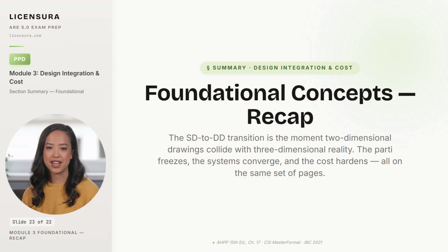If you remember one thing about design development, remember that it is not a polish phase. It is the moment 2-dimensional drawings collide with 3-dimensional reality. The party you sketched in schematic design freezes into a fixed armature. The engineering disciplines bring their systems into the same set of pages. The cost estimator hardens the number against a budget, and code review begins in earnest. The architect who runs the integration rhythm, frozen party, hardened cost, coordinated systems, complementary documents, is the architect whose design intent survives into construction.